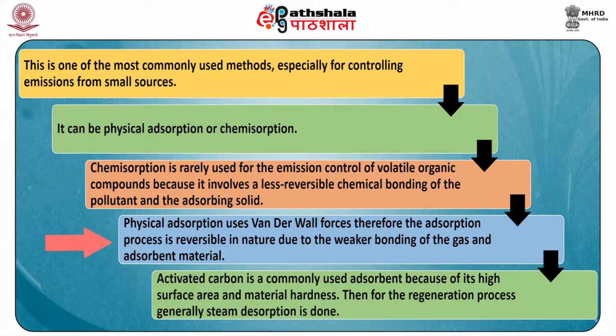Physical adsorption uses van der Waals forces. Therefore, the adsorption process is reversible in nature due to the weaker bonding of the gas and the adsorbent material. Activated carbon is a commonly used adsorbent because of its high surface area and material hardness. Then for the regeneration process, generally steam desorption is done.